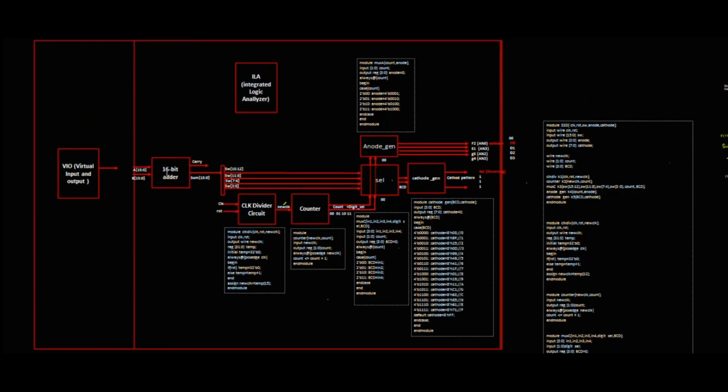So now what I do is I will be using the option that I have on the Vivado, that I can use an integrator block where I can integrate the ILA as well as VIO. There are two dedicated integrator modules, IP modules, that we have. With the help of these two, I will be adding my RTL block. This is the entire RTL block. I will be integrating these three blocks and creating an HDL wrapper, and that I will be creating as a top level block, and that top level block will be added with the XDC file, user constraint file, and with that I will be doing the dumping process as usual like we have known in the previous session.